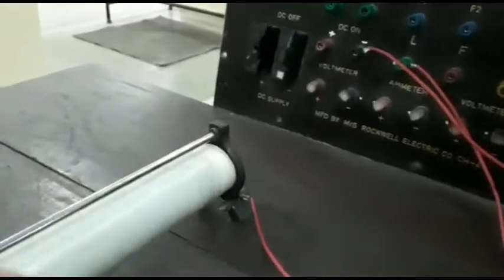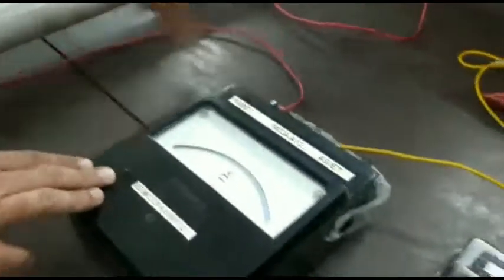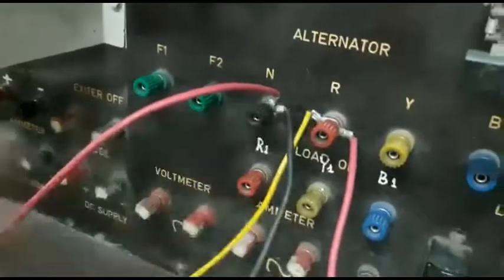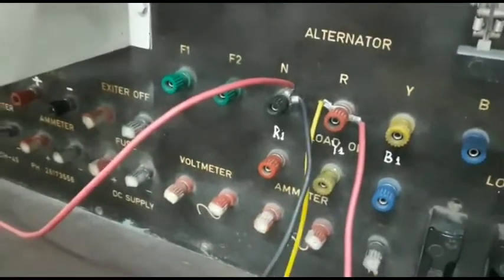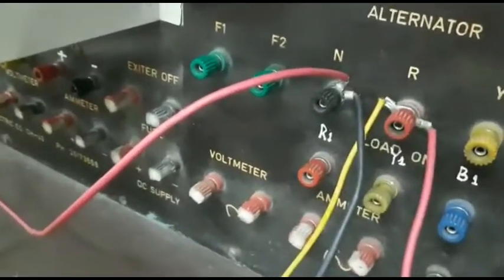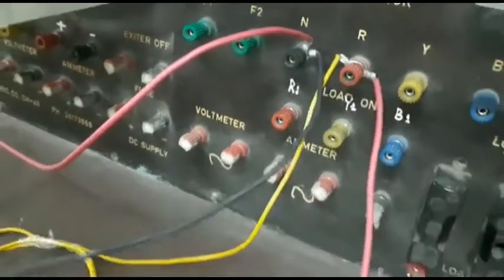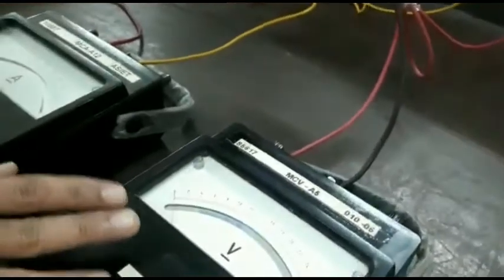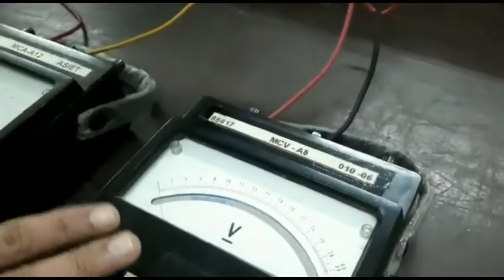From the rheostat, we are making use of a 100 ohm 4.1 ampere rheostat. From the rheostat, it is going to a DC ammeter. And from this DC ammeter, the return wire is going to the R phase here. That means the rheostat and the ammeter are connected in series. Now you have a voltmeter that is connected between the neutral and the R phase. It measures the per phase voltage, the voltage that is available across R and N.